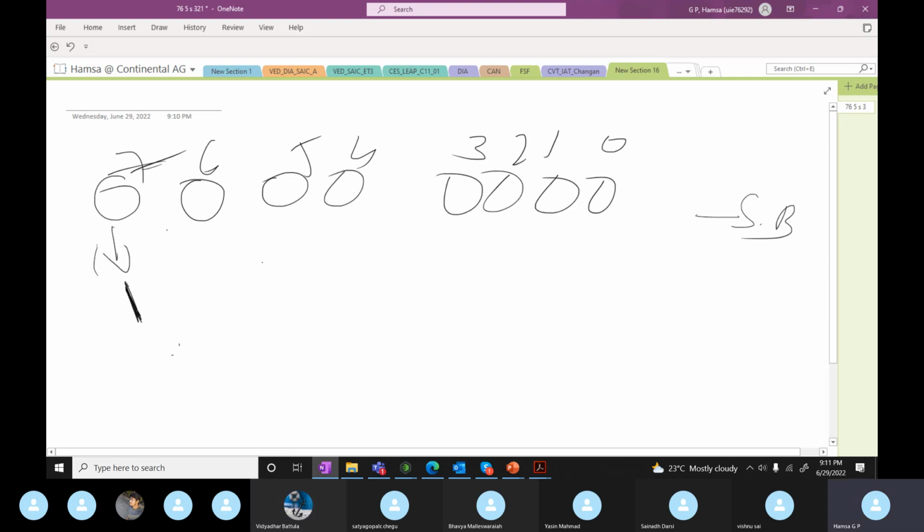In hexa, I'm asking. Tell me this value in hexa. Now the seventh bit is 1. Nothing but there is a camera input request, and the ECU is not getting that camera input. So it has set the fault, and that fault has this warning indicator high.